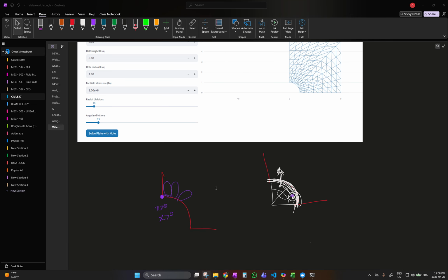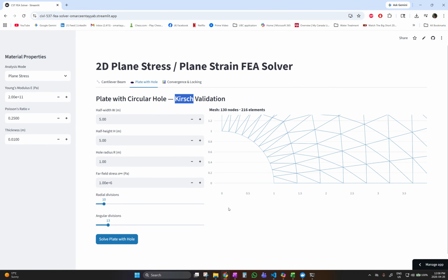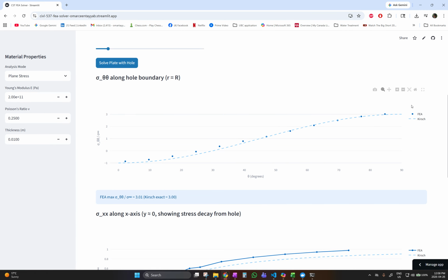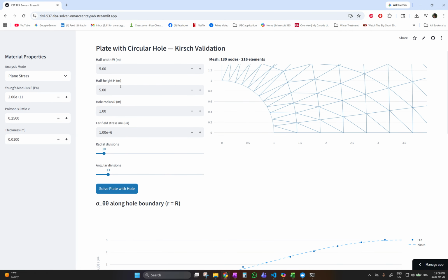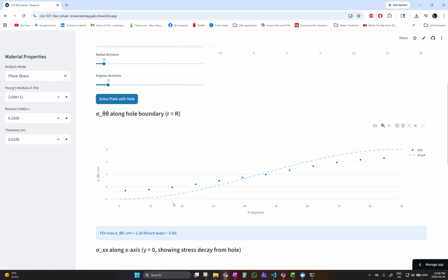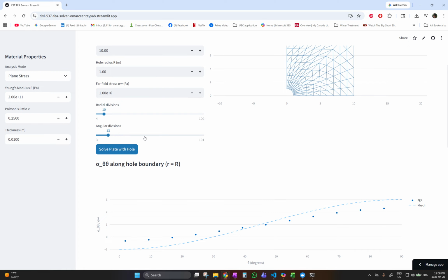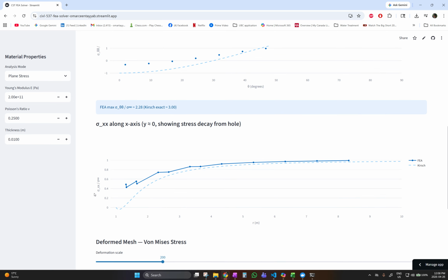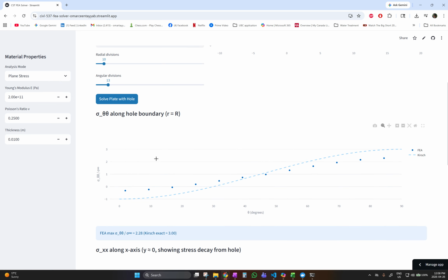And so that's the issue. Anyway, this has been the longest discussion on this. I want to move on and show you that it works. Fantastic, it works. Look, and I want to change this to my actual conditions and solve it. As you can see, when I set those ratios, it dampens it, but upping the mesh density brings the solution back to convergence, because it does a better job at approximating that hole.